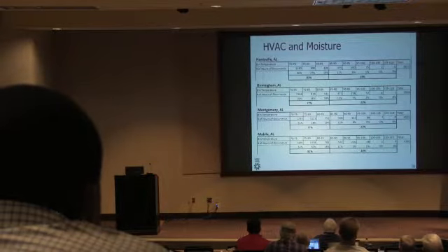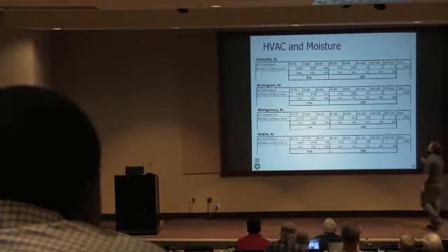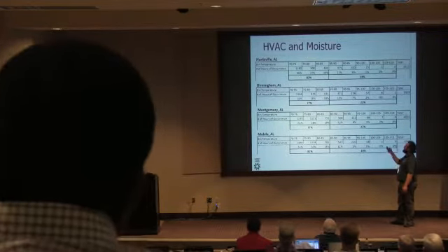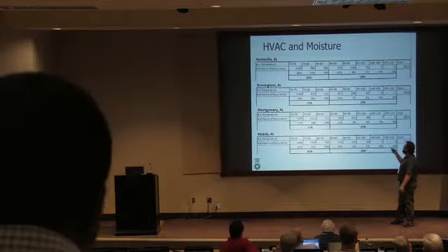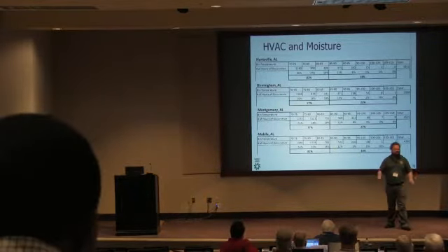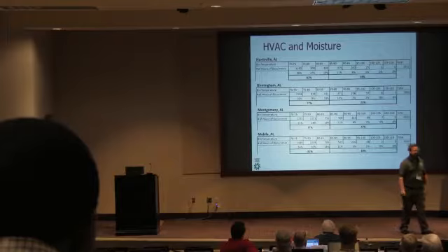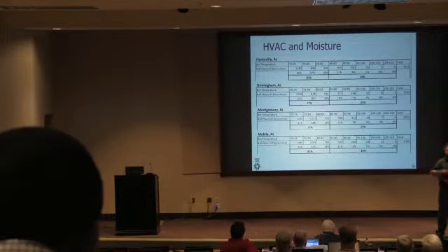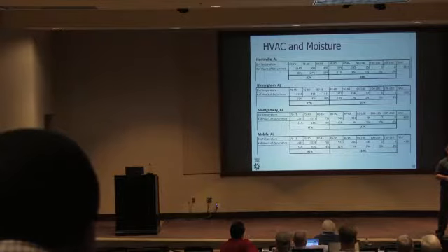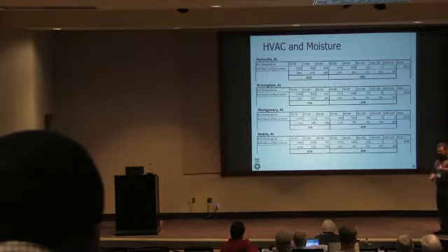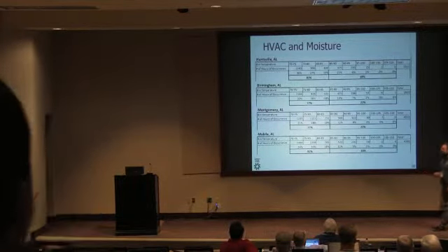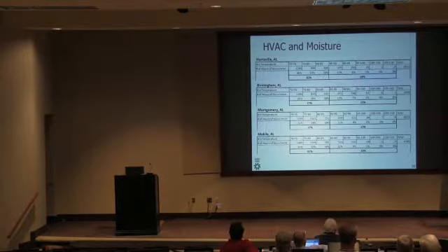And so what we really find is that reaching temperature set point with equipment, and having equipment that can operate effectively up to the ASHRAE design temperatures and down to the ASHRAE design temperatures, is not a problem. Managing the indoor humidity level is a big problem in our climate zones. And that's really the comfort factor that's driving a lot of our issues. Not to mention mold and mildew and indoor air quality problems. So the old saying is true, in the South, it ain't the heat, it's the humidity.